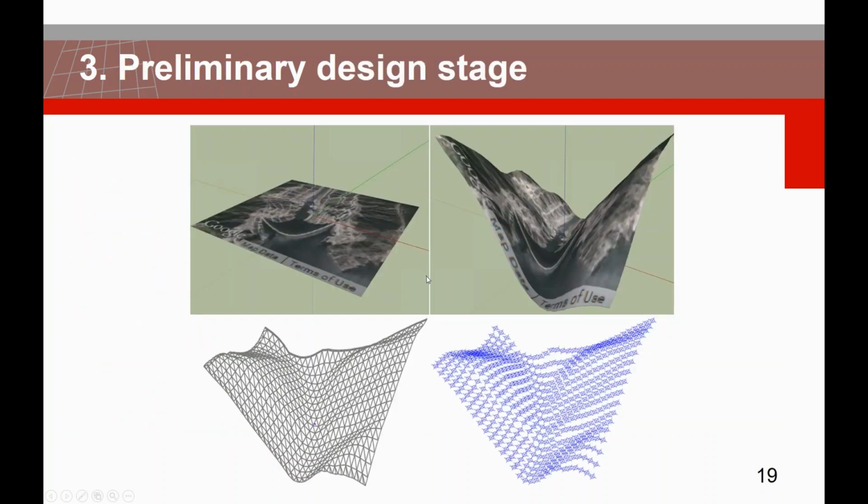For example, in our process, we used the second option, where we went and found a reference site through Google Maps. For this reason, we used SketchUp. As you can see here, we see the picture of Derner Dam, which is located in Turkey. Then we converted it through SketchUp into a 3D surface that we exported into a CAD file, and we took out the cloud of points.